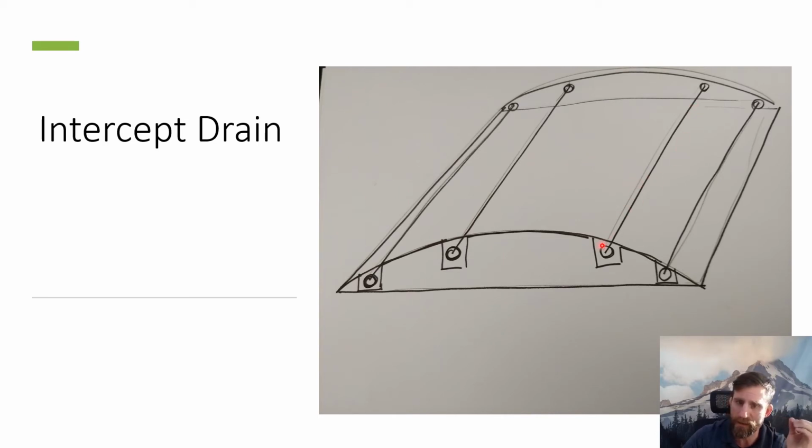So anything that's not draining down will now start to roll off the surface. Once it finds its way to this intercept line that's filled with sand or fine gravel to the soil surface, it now can infiltrate down quickly into the drain line, which has the drain tile that moves the water off the soil surface. So that's a drawing of how a slope and intercept drain tile system would work together.